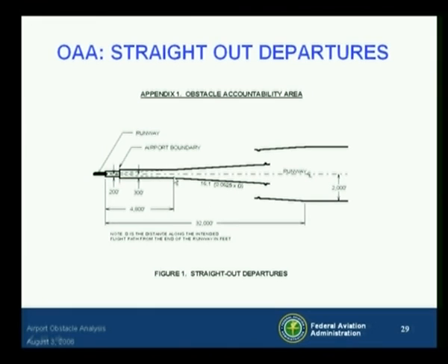That's the point where you bust through the regulatory 300-foot plus wingspan corridor. If you take 32,000 feet times 0.0625, it equates to 2,000 feet. And at this point, the splay turns and parallels the net flight path. And then the 2,000 feet either side of the net flight path becomes a parallel protective function.